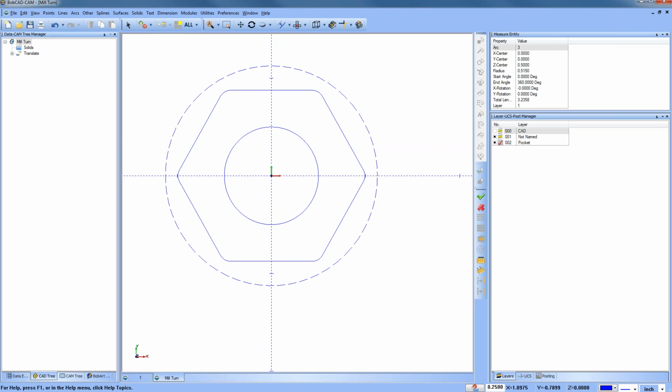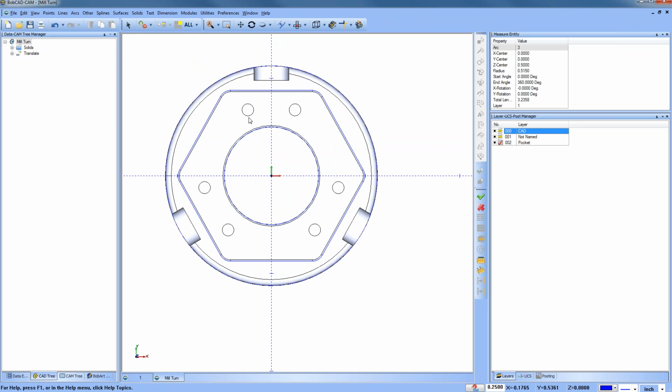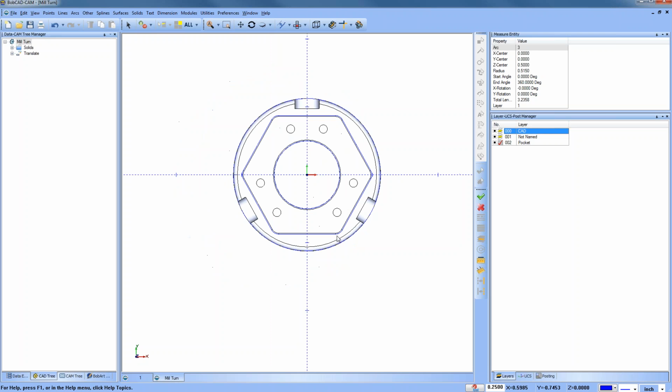And this is my CAD prep that I would use for the face milling. I'm going to be able to do an open pocket from this outside here. I can do a spiral pocket here, and then I can work with the model for the whole location. So that's what we're looking at. So I've done my CAD prep. Let me see if there's anything else. We have the part location. We did some measurements. We created the face pocket.